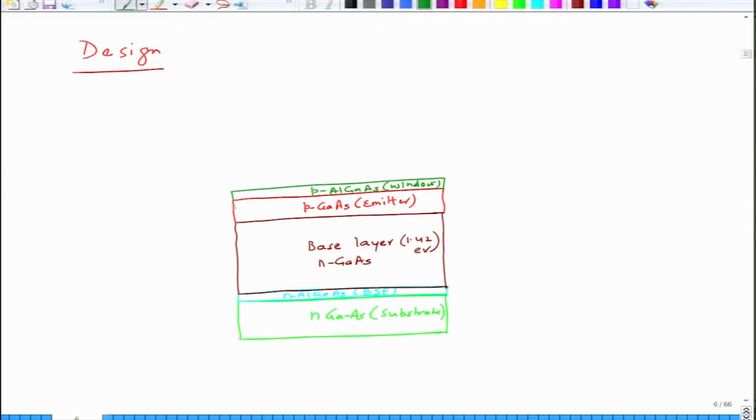And then we have on top a layer of zinc sulphide and magnesium difluoride, which is ARC essentially, okay. So, you can say it is ARC. And then we have a heavily doped region on these sides, P plus gallium arsenide, okay.